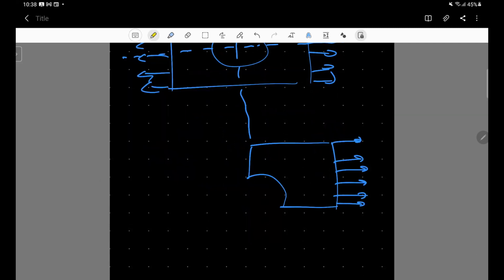We can apply fixed boundary conditions at this location as well as this location to mimic the total system. By applying such boundary conditions, you can simplify the problem and analyze only 1/4 of the problem, meaning the number of nodes and the elements tend to reduce by approximately 1/4.